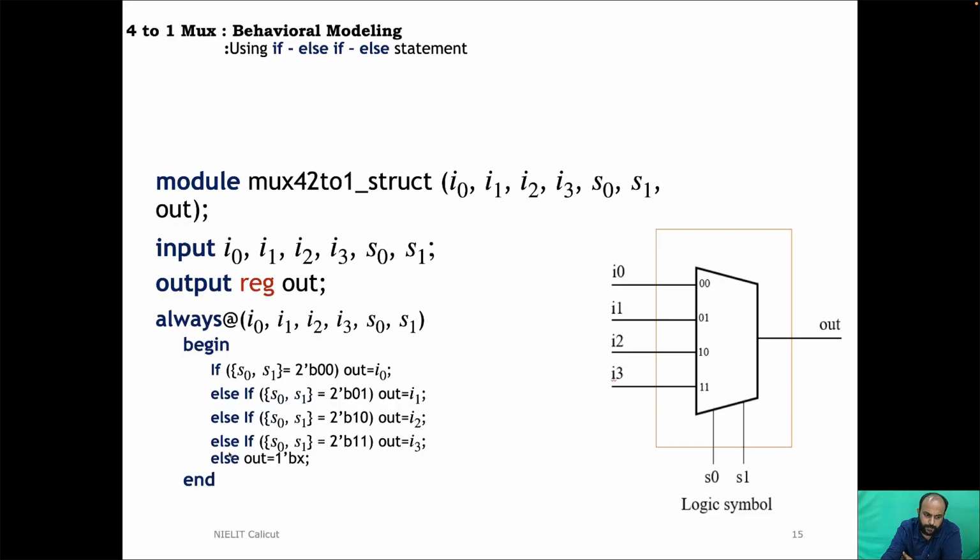Though we see here 1 2 3 4 5 lines or so, if else is a single statement. So it is not a must that we write begin and end. Begin and end are used for combining multiple events that happen sequentially. But it doesn't hurt to give that as well. If you would like to give it a more structured view, you can always add a begin and end. It just serves the purpose of opening braces and closing braces. Anything which happens within begin and end happens sequentially. So that completes it.